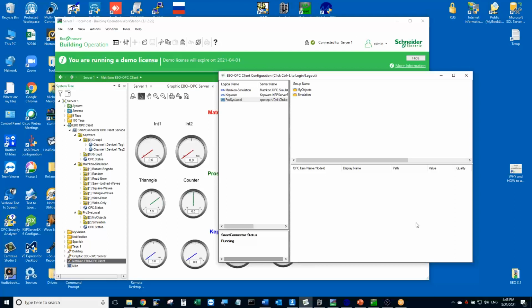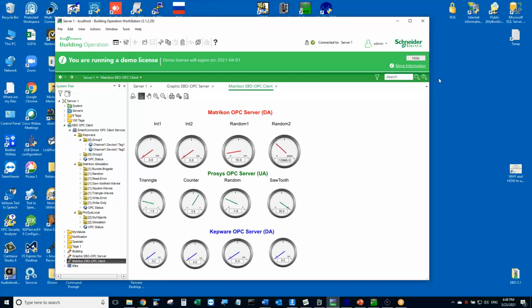There's no hard-coded limit. Obviously, it's limited to the resources of your PC. Inside a SmartConnector, by default, we have what we call processor threads, which is how many threads are being used to run custom code. By default, there are 5. That can be increased as you need, up to the max of whatever your PC will consume. The EWS server stuff, like the OPC stuff, is done separately. So it really depends on the resources on your machine. There's no hard-coded limitations.